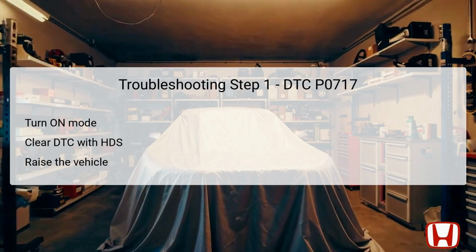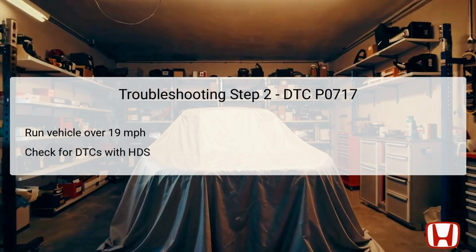The second step involves running the vehicle at speeds exceeding 19 miles per hour for a minimum of 30 seconds. This test is vital as it simulates normal driving conditions, allowing the input shaft speed sensor to function within its expected range.